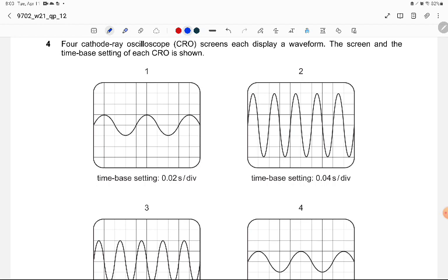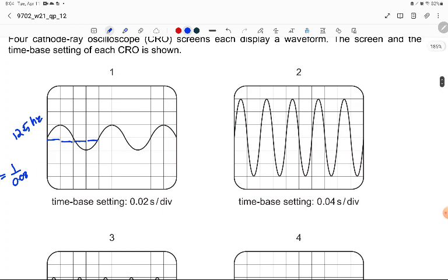First we will find the time period, and after that we will have to convert this into frequency. So let's see, 4 boxes over here, so we'll get our time period. I'm just going to be doing it very quickly. So frequency should be equal to 1 over time period, and for this one we are using 4 blocks. So 4 blocks would mean 0.02 multiplied by 4 blocks, and that gives me 0.08. So 1 divided by the answer should give me 12.5 hertz. That is 12.5 hertz.